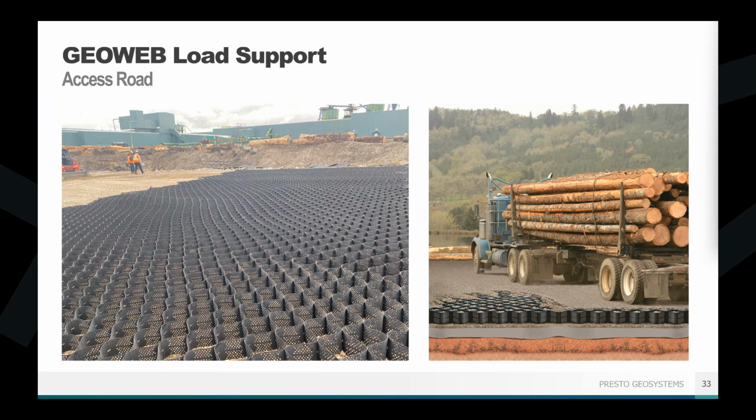If you're not worried about drainage, if you're in a very arid environment, or you have other drainage infrastructure set up on site, great, use it, 100%. But if you know that drainage is a concern, if you know that stormwater management is something that you need to prioritize, that's something that we can focus on, and it will influence what type of infill material might be the best choice. So just something to keep in mind.